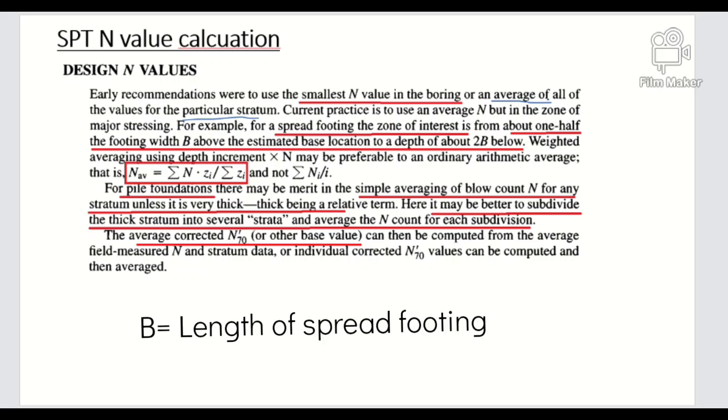And over how much distance do we have to take the SPT or N value? If it is a spread footing, it is about 1/2 the footing width above the base, and to a depth of about 2B, twice the width of the footing, below the base.